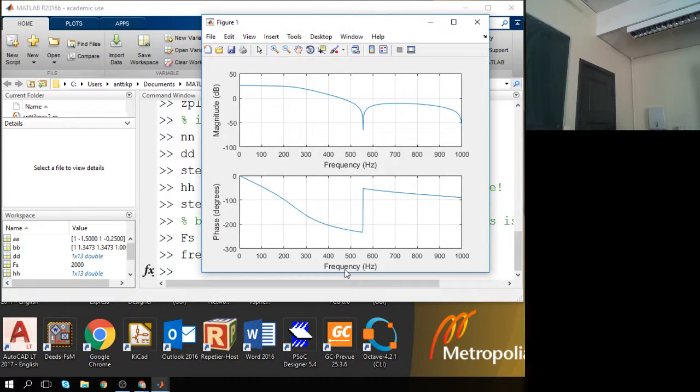And here you have the magnitude in dB. Then we also have the phase response, decreasing as a function of frequency. This is the passband, which is the most important part. And as we can see, this is definitely not linear. So it deviates from linear quite a lot, actually.